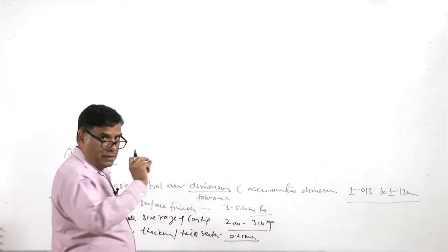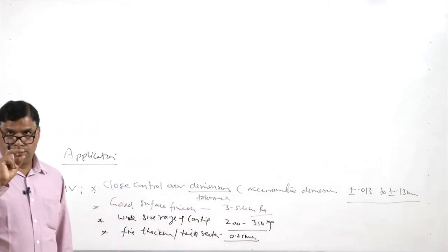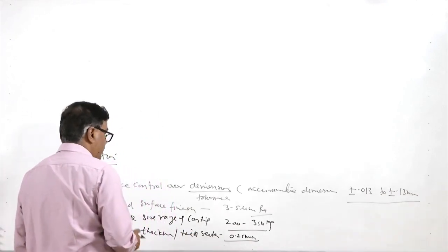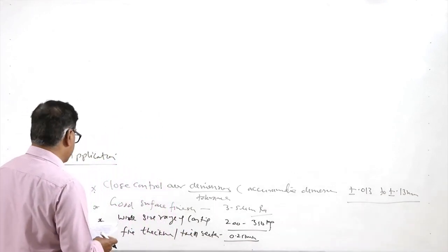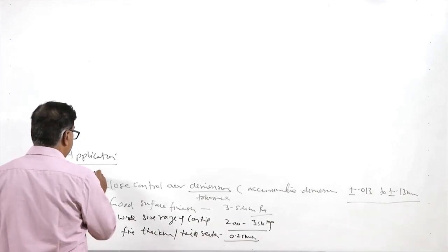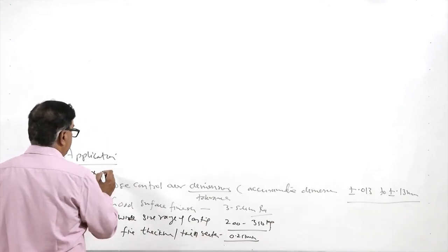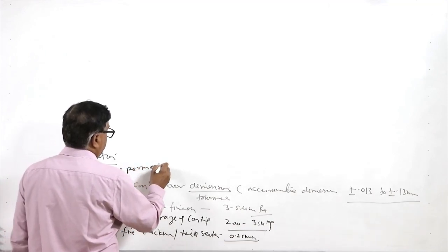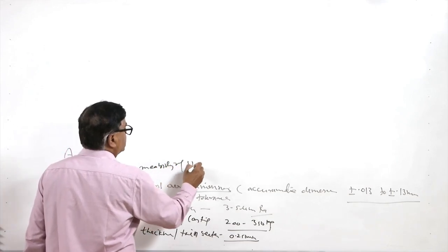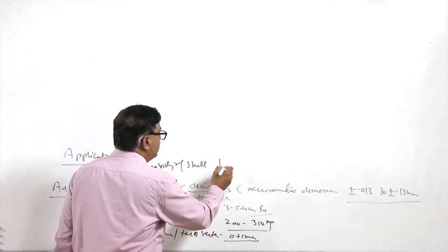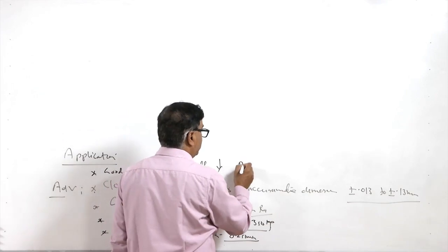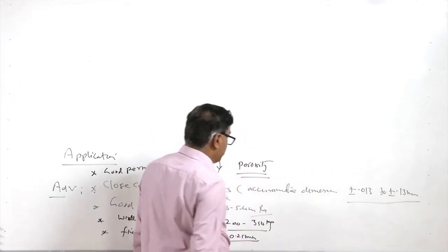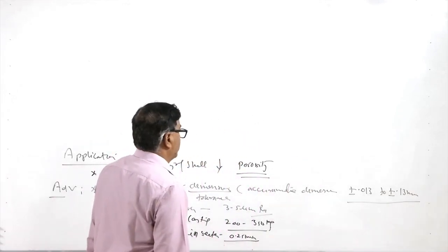So, features of 0.25 mm thickness can also be produced with the help of this casting process. Since the permeability of the shell is good, it reduces the scope for porosity. So, the casting is sound and by and large free from porosity.